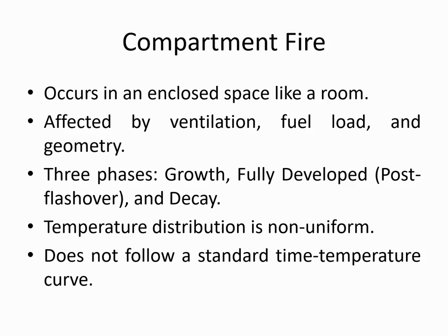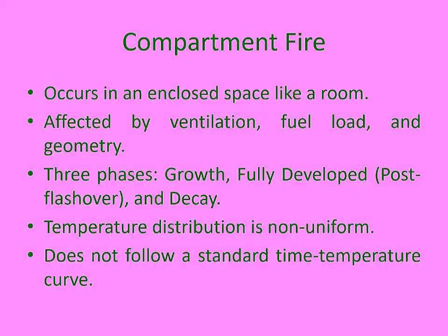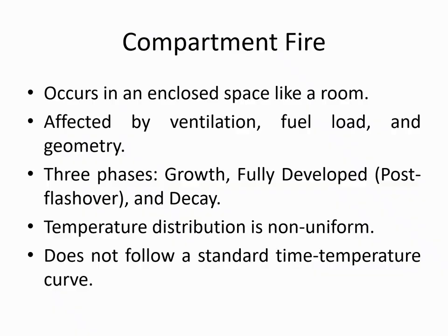Let me compare the fire severity between component fire and furnace fire. Let me move into the component fire. This component fire occurs within an enclosed room or space. Its behavior depends upon three major factors. First one is ventilation of the room, whether the room is enclosed or has any open space. Second one is fuel load, whether the room has any fuel materials like paper, wood, plastic or not. Third one is geometry of the room.